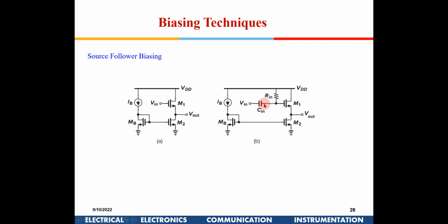The gain of the source follower is I think gm RS by 1 plus gm RS. Yes, you have to keep gm very, very high to get close to unity gain out here. If we increase this gate voltage to VDD, how will this help the cause?